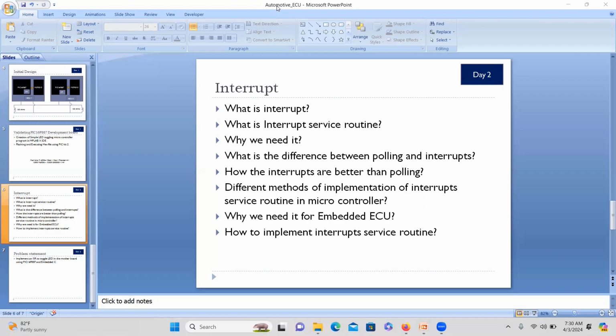They should be serviced when requested, right? So when the interrupt occurs, program control will be transferred to that interrupt function and it will execute that function. The number of program lines executed when a particular interrupt occurs is called the interrupt service routine. We have seen two things.